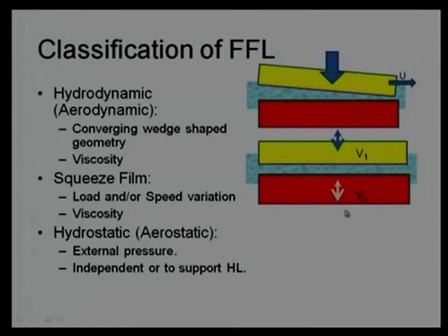Velocity of the second block is also changing, but not necessarily do both blocks have to have a relative velocity. You only need to have a velocity component. If there is a velocity v1 and there is no velocity v2, and velocity v1 itself is fluctuating, even in that case squeeze film action will occur.